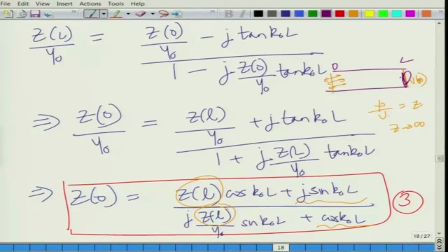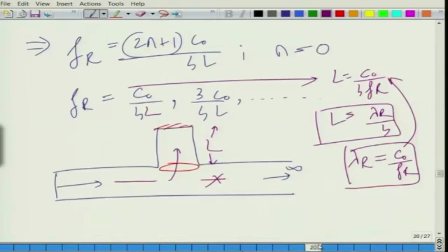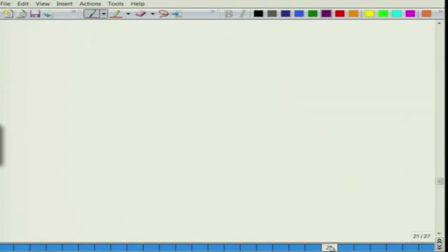That will basically complicate problems, and this is important because not only in the side branch resonators is noise radiated in all directions; we also have things like the end plates of mufflers. No matter how thick they are or how properly you weld them, they are going to vibrate a bit, and that is going to have a major effect on the structural acoustics part, or the breakout noise, as it is called. We will talk about that later, but another expression we can derive quickly is for the impedance.